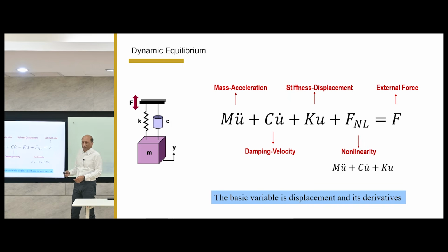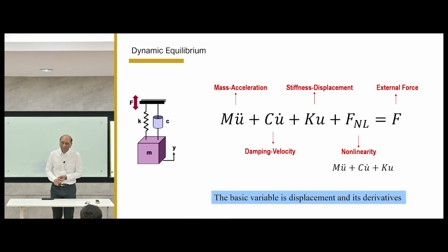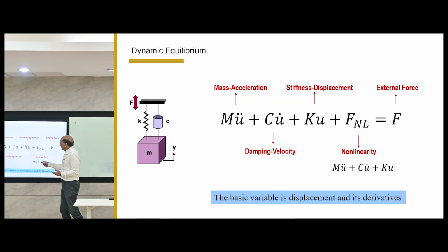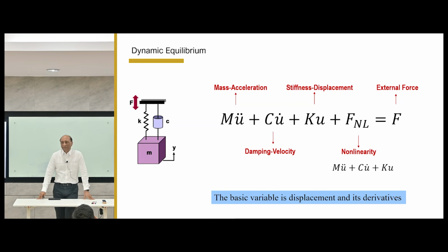And this is the nonlinearity correction, which again depends on the whole, because the damping can be nonlinear, stiffness can be nonlinear, even the mass, although normally it doesn't change, but you can put that in. So the equation now needs to be solved by iteration, because this equation includes itself. Okay, so that's the story behind the whole analysis.